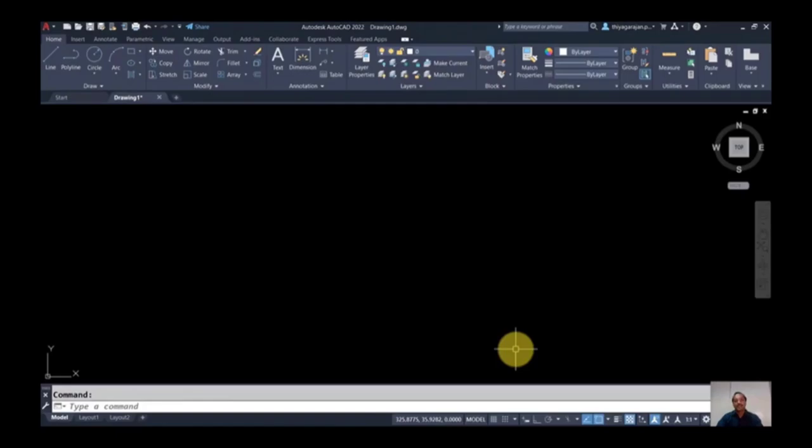This is our AutoCAD screen. As usual, I set all the limits and settings. Let me go for the text command. Once I give the text command, as I said before, style is standard, default height is 2.5, justification is left. Annotative is no at present. What does annotative no mean? I will tell you later. Start point: let me start the text here. And specify the height. Let it be the default height.